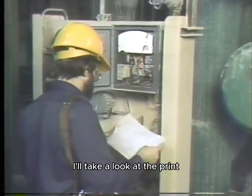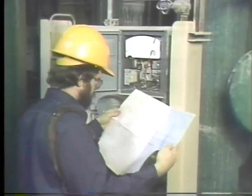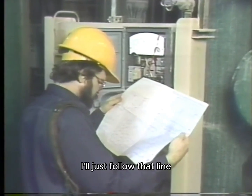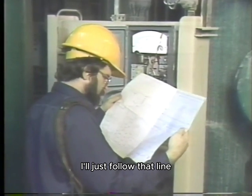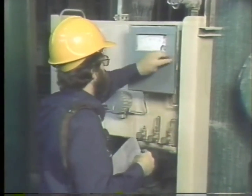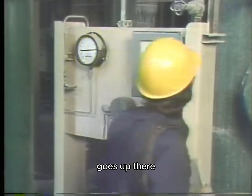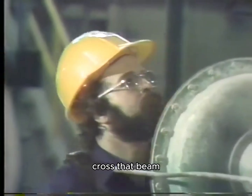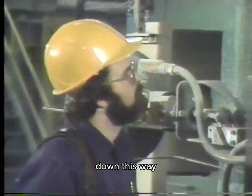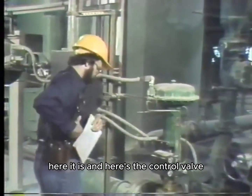I'll take a look at the print and see where the output of this controller goes. It goes to the level control valve. I'll just follow that line, see if there's any damage in the tubing. See, it comes out here, goes up there, across that beam, down this way. Here it is. Yeah, here's the control valve.